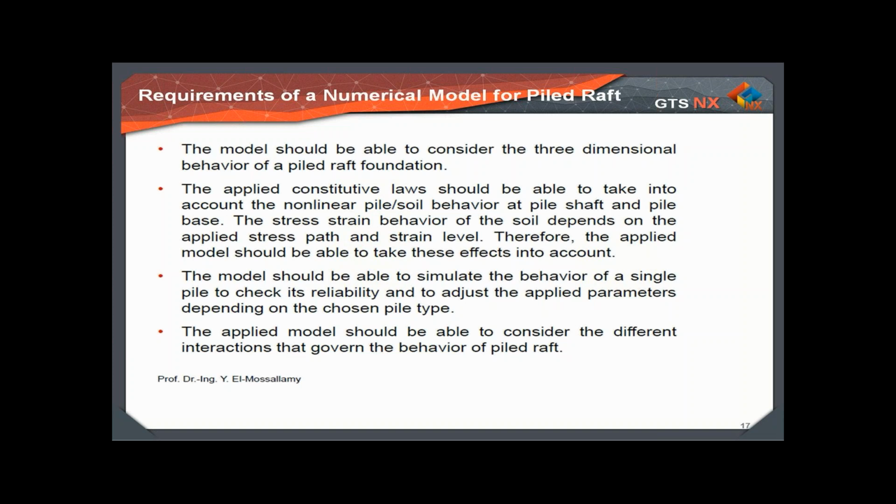So, the constitutive laws govern the pile-soil interaction, and the soil behavior itself should be capable of handling these interactions. The model should be able to simulate the behavior of a single pile to check its reliability and to adjust the applied parameters depending on the chosen pile type. Here we refer to what we call the calibration process. So, if we have results from a pile loading test, you should be able to simulate this pile loading test properly in your numerical tool. And then once you are able to capture the behavior you have in the pile loading test, you can go back and utilize these parameters in your full structural numerical model.